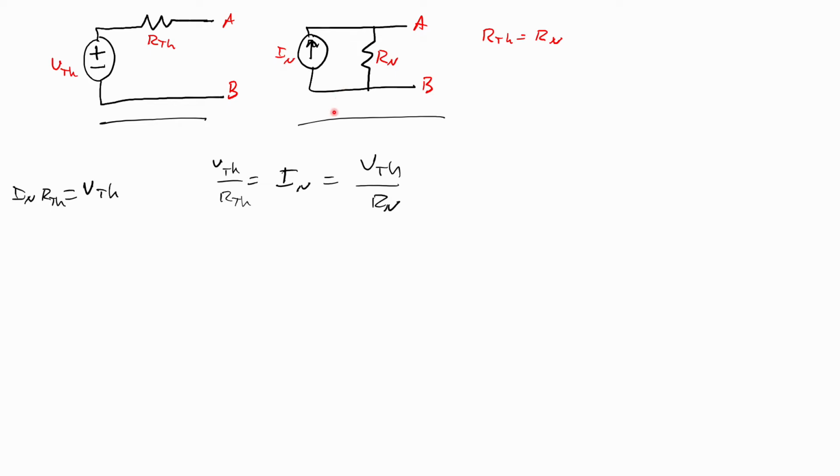Yet when we're building an amplifier, we're looking for voltage in and voltage out. So you often would use a Norton circuit to represent the transistor, but that's inside an amplifier, which we're really looking at as a kind of Thevenin circuit. So it's pretty useful to understand them and to be able to convert back and forth without any question or time. Just immediately see it and just do it.